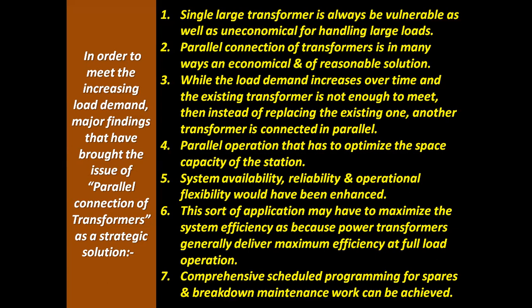Number 4, parallel operation optimizes the space capacity of the station also. Number 5, system availability, reliability, and operational flexibility would be enhanced. Number 6, this sort of application may maximize the system efficiency, because power transformers generally deliver maximum efficiency at full load operation.